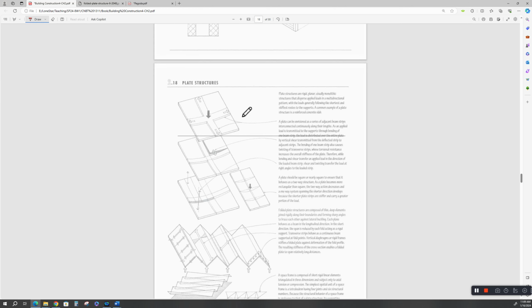Now, plates can be out of steel, they can be out of corrugated metal that is all welded to the substructure, or they can be in reinforced concrete. If this was reinforced concrete, then this would be a two-way slab. You have force resistance that way, and you've got force resistance this way. But you've got to account for being able to support it on all the sides, all four sides. Right? You've got to transmit those forces to something. All right.